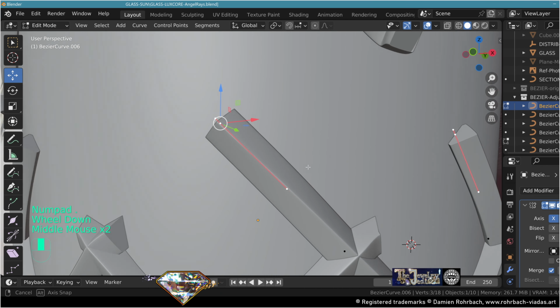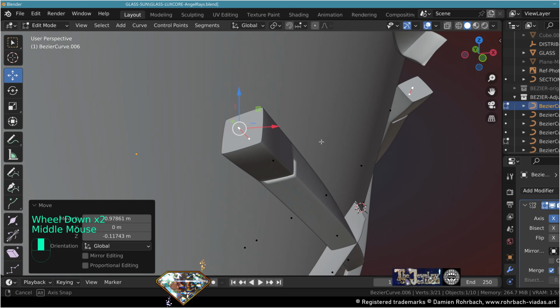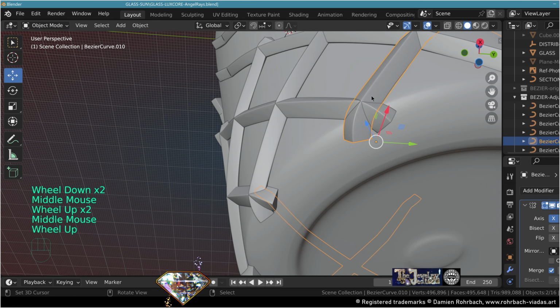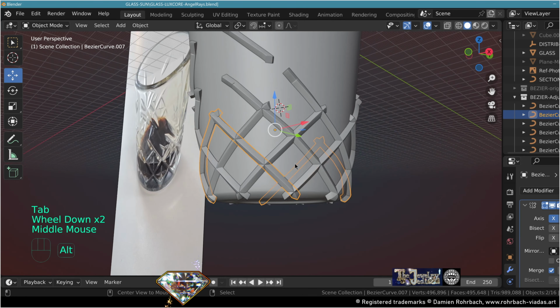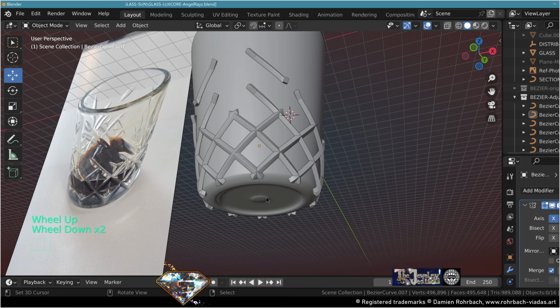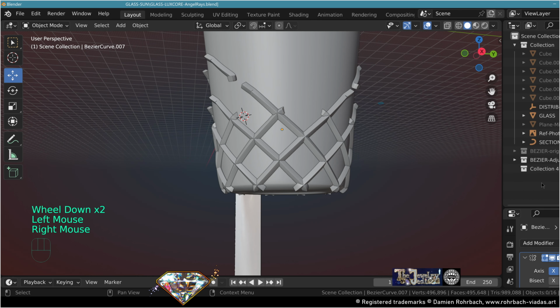So here I'm going to do it. So it's just an extrusion. Keep the angle here straight. And like I said, these are link copies. And like I said, you need to extend the ending of all the curves. We'll have perfect sharp corners at each ending, okay? But to do that, I have to make them as meshes, because as you know, we can't make booleans on curves. But now I'm going to create a new collection, and these will be meshes.